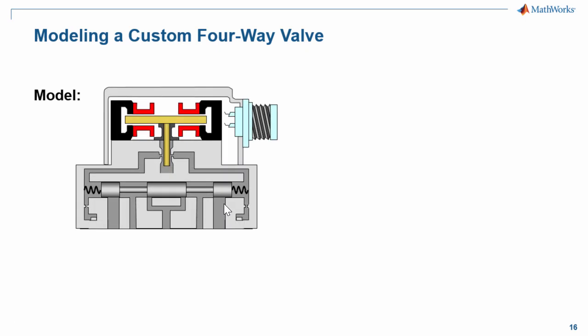The structure of the valve we wish to model looks like this. It has the same connection ports to the pump, tank, and A and B ports. However, the spool dynamics are included. An electromechanical actuator controls the flow of hydraulic fluid within the valve so that the hydraulic pressure moves the spool. When the spool moves, it connects the tank to the B port and the pump to the A port. It can operate in both directions.